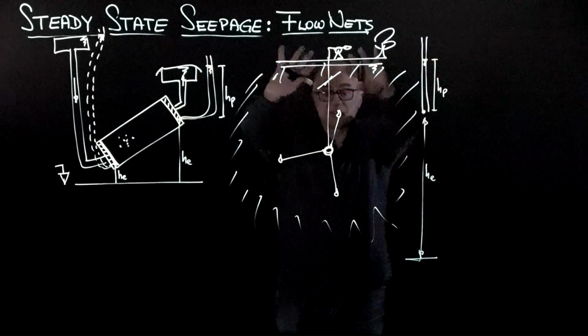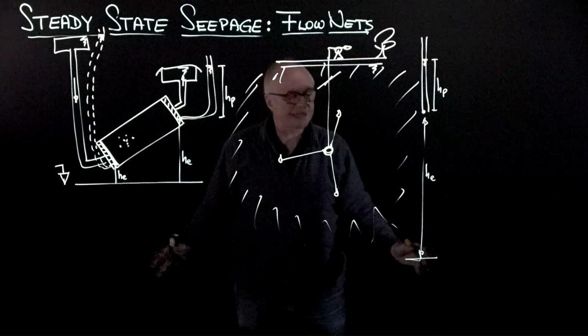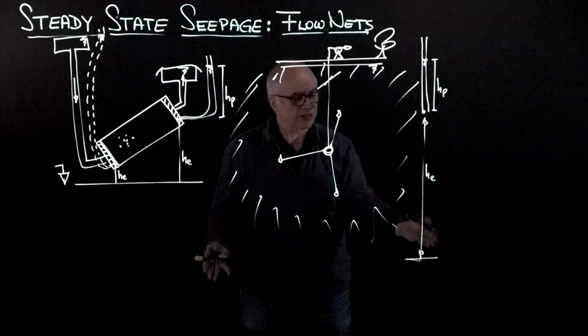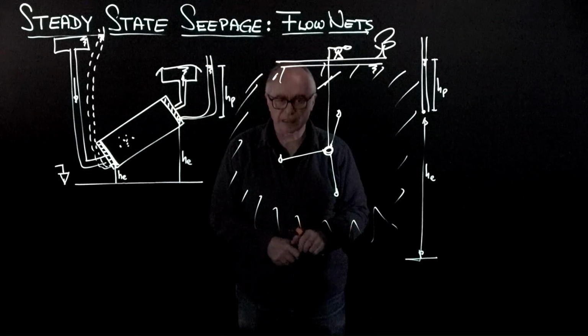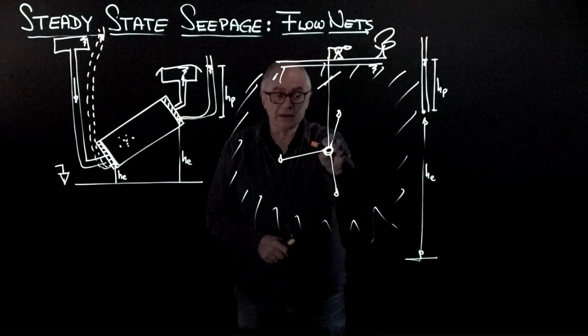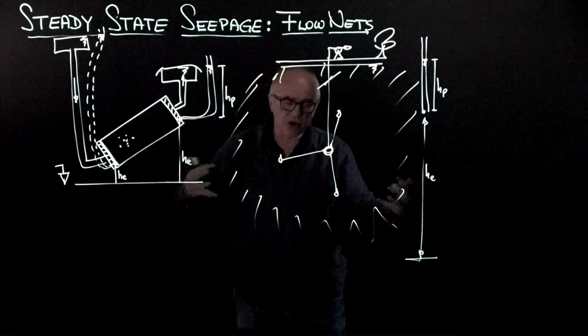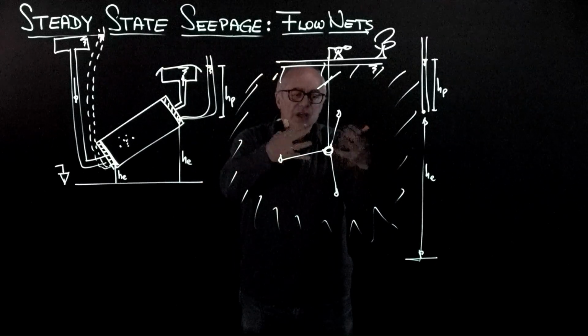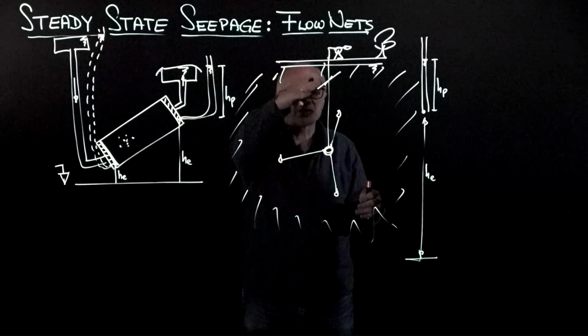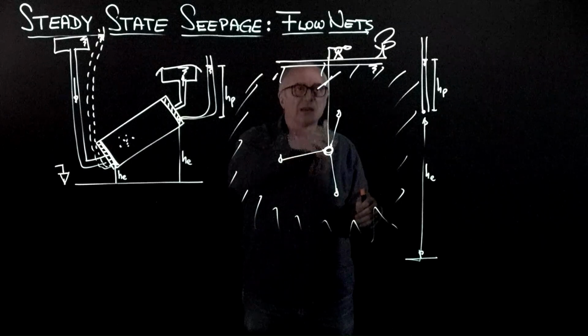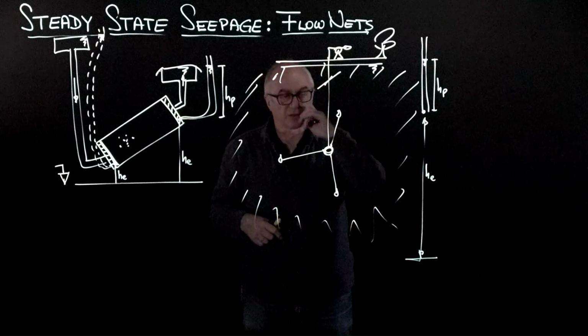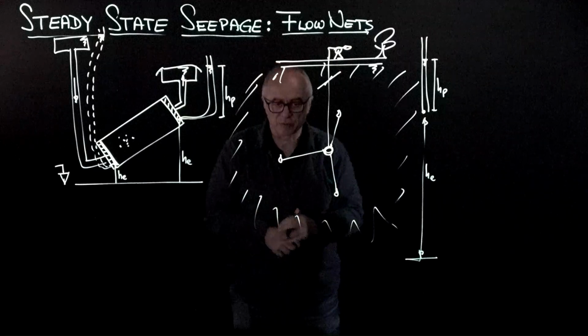And so in the far field, everything has the same total energy, which is captured here. In the near field, the last equipotential where all the water goes to converge, it will be determined by how much you depressurize the well as you pump, not from the top, probably from a submersible pump.